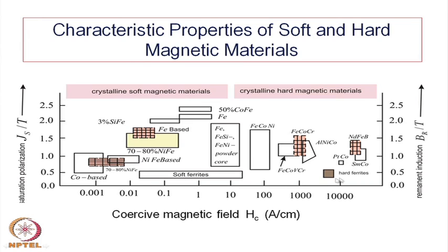However, it has a tremendous application. Whereas if you talk about the saturation magnetization, it is very high even for these soft ferrites. And so far as the permanent magnets are concerned, these are the best quality magnets one can have. Earlier, of course, these were alnico and permalloy. These are the materials used as permanent magnets. Now, this is the soft ferrites region.